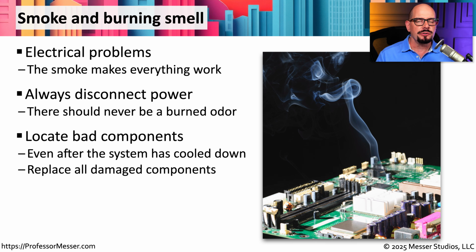Once the smoke is cleared, you can remove the case cover, have a look at the motherboard and other components inside of your system, and see if you can visually find where this particular problem occurred. Often it's something that's very easy to see, but if you're not able to visually see it, you may be able to smell where on that motherboard you're having a problem. You obviously want to determine if it's part of the motherboard that's damaged or an individual component, and swap that component or motherboard out to be able to get this system back up and running again.